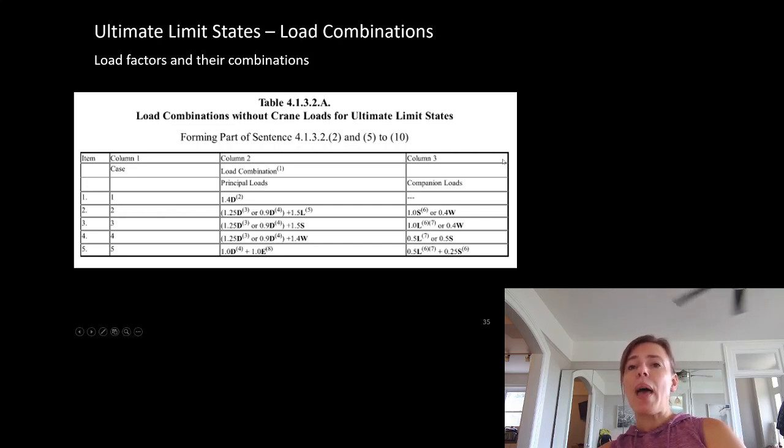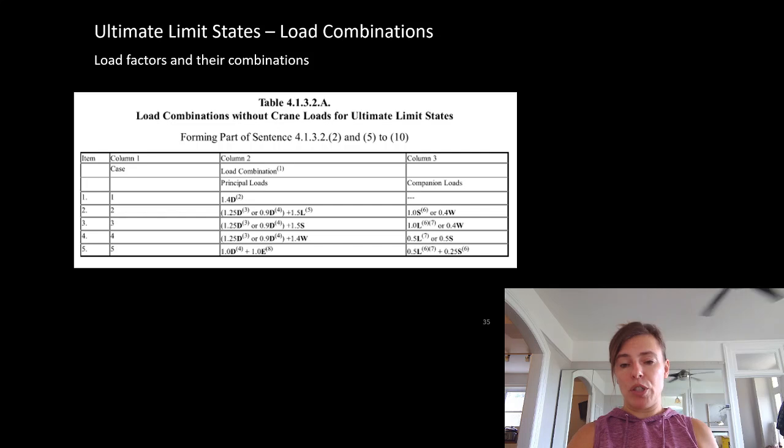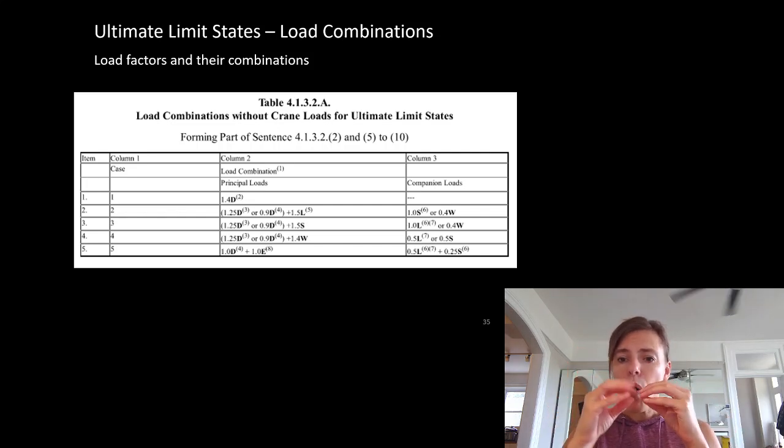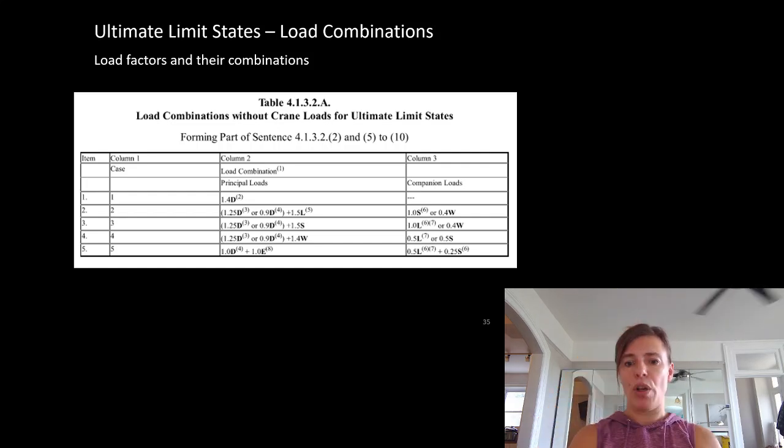And then we do that with live and wind, or we might need to think about companion loads, but only if they're acting in the same direction. So you really have to stop and think about it. You have to think about what direction they're acting, and are they adding up or subtracting from each other? Because if they're subtracting from each other, you want to get the worst case of the load acting downward and the worst case of the load pulling up.